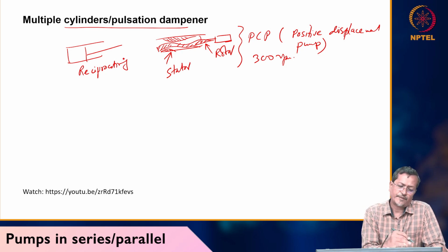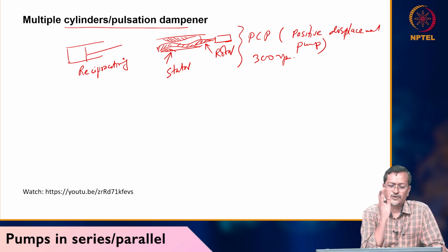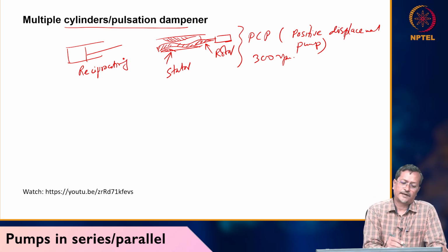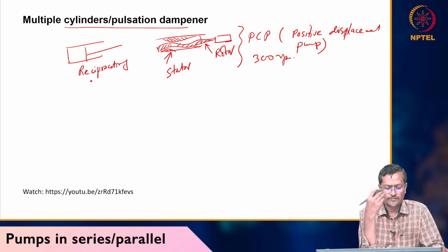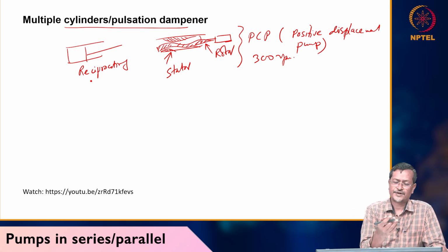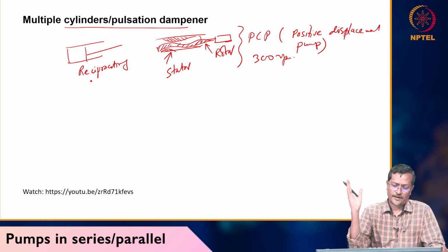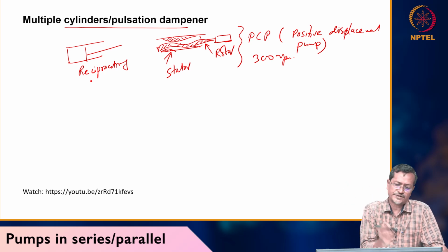And for a reciprocating pump, you cannot increase the pump speed to a very high level. For example, you may have 10 strokes, 20 strokes, maybe 1 or 2 strokes per minute; 100 strokes would sometimes be too high. So 10-20 times it is pushing and pulling, delivering fluid, which can be okay for a reciprocating pump, maybe 10-20 RPM.